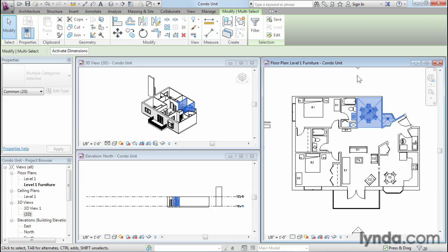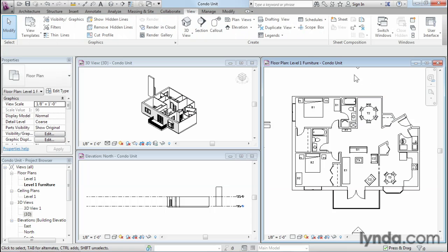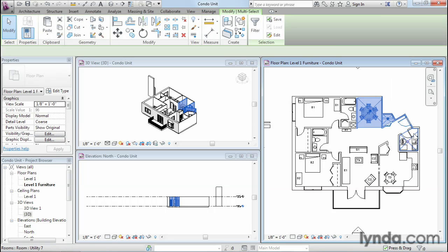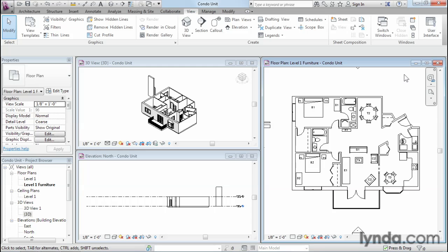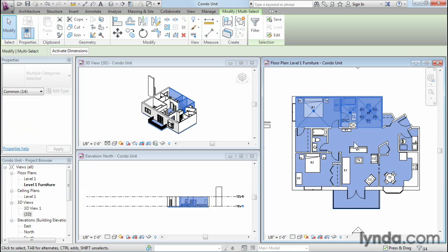Crossing works the same way. Where window was left to right, crossing is right to left. Notice the dashed edge versus the solid edge, but in other ways, it works exactly like the AutoCAD counterpart. Now all we have to do is touch the object and it will be selected. So using windows and crossings is usually the fastest and easiest way to make selections. And again, it's very similar to the AutoCAD counterparts, except that you have to drag your selections instead of clicking them.